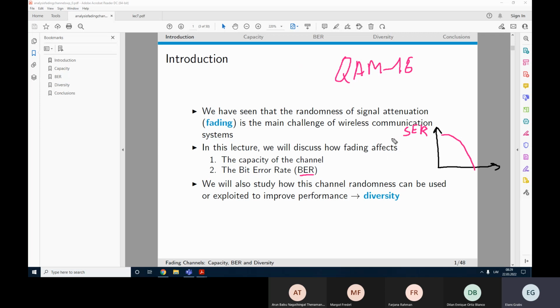But you need to remember that we actually used gray mapping for our constellation. Let me draw part of this constellation. We tried to assign the code words consisting of bits to each of the constellation points so that the difference between code words would be minimum. For example, here we have 0, 0, 0, 0. Here we are going to have 0, 0, 0, 1.